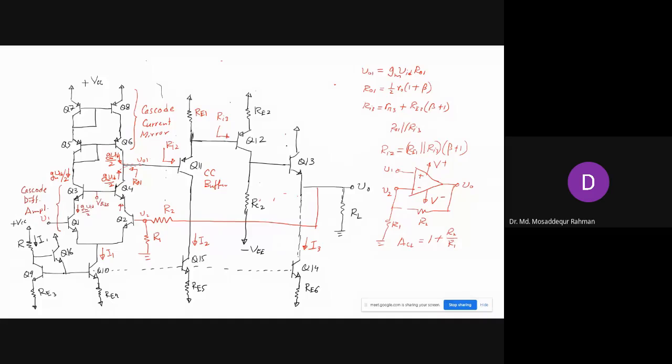And the output stage is very critical. You choose the output stage, the rating of the transistor used, depending on the current, voltage and power requirement of your load, right? If you need very high currents in the range of amperes, then you have to use a power amplifier, maybe a Darlington pair, at the output stage.